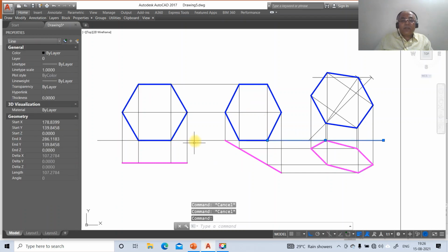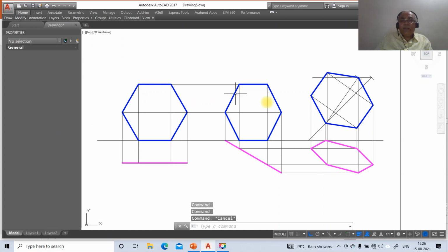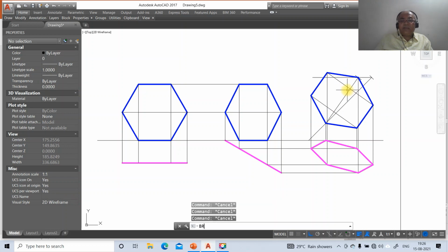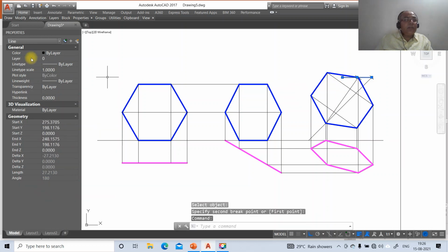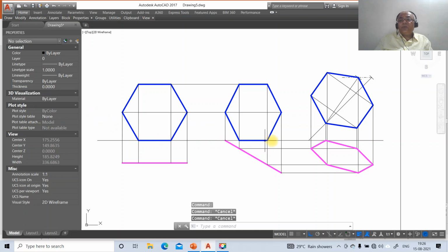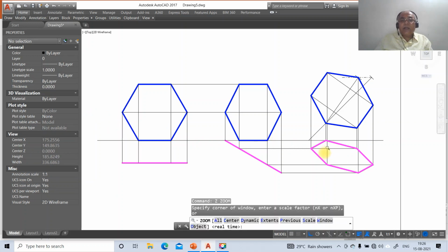Then you just click over this and click over this and click over this and change that layer to XY. And now you just break this line till here, and now you just click on this, go to layer, make that layer as locus layer and change the line weight as 5. So once you do that, you're going to get the locus line type.